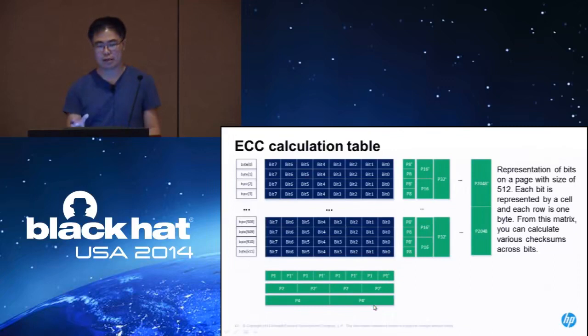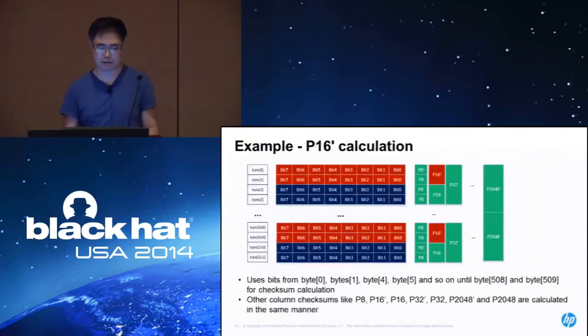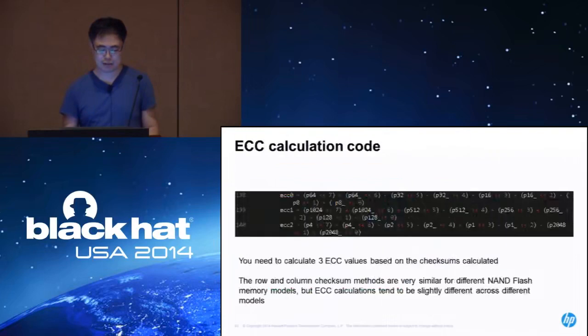So by knowing which checksums are wrong, you can exactly pinpoint which one bit made the checksum error. And a checksum has only two states, 0 or 1. So if it is wrong, it will be the other one. In that way, ECC can fix bit errors. So that is the basic concept.